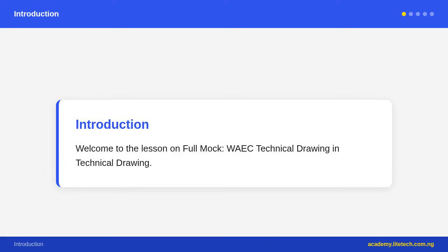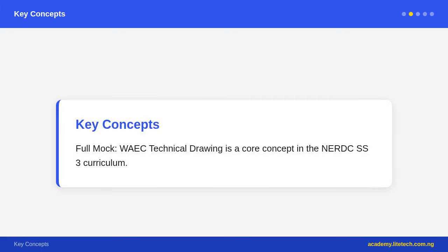Addendum circle, tip circle, the outer diameter of the gear. Addendum equals 1 module above the pitch circle. Tip circle diameter equals number of teeth plus 2, times module. Dedendum circle, root circle, the inner circle at the base of the teeth. Dedendum equals 1.25 module below the pitch circle. Root circle diameter equals number of teeth minus 2.5, times module.